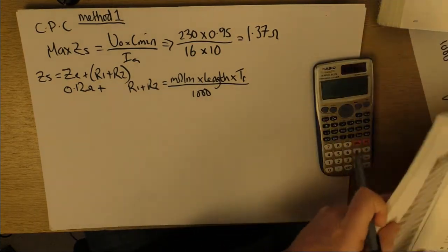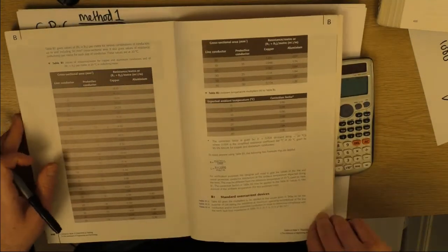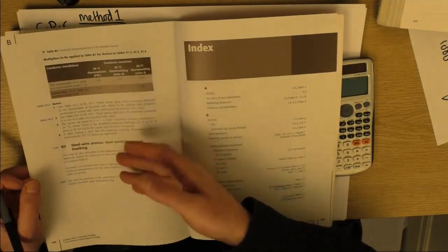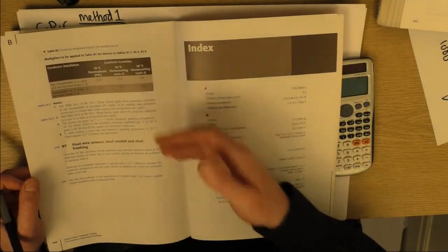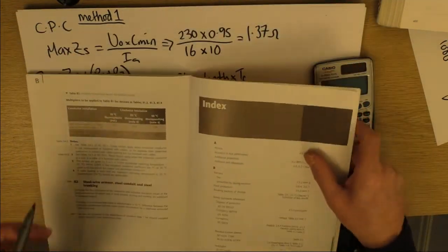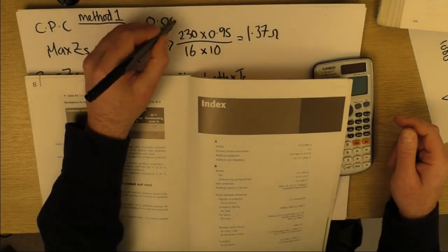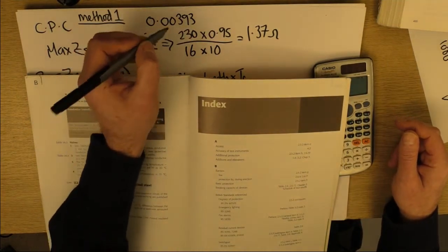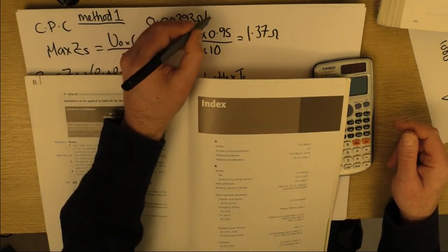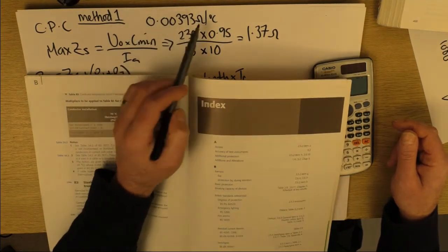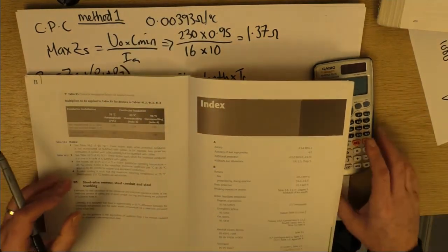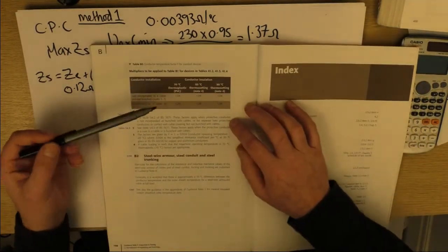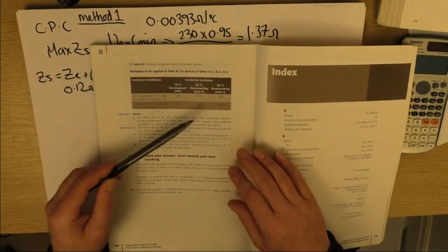Temperature factor, and that's been done for us. Just know that these correction factors have been done for us, but it's down to the fact that copper increases its resistance by 0.00393 ohms per degree C. I've done a video about all this, so check it out if you're interested. But for what we're doing, we need to use this factor.